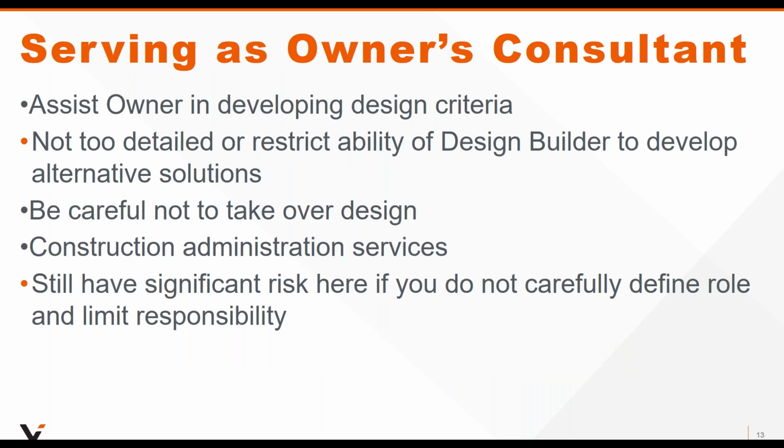So let's talk briefly about what happens when you're serving as that owner's consultant. You're not part of a design build entity, but you are indeed serving as a consultant for the owner. You're assisting the owner in developing design criteria, and the guidance that's provided to you is that it shouldn't be too detailed or restrict the ability of the design builder to develop alternative solutions. The whole idea is that you want the design builder to use their expertise and their smarts to go out there and provide a solution that works. And so you want to give them enough information, but it shouldn't be too detailed.